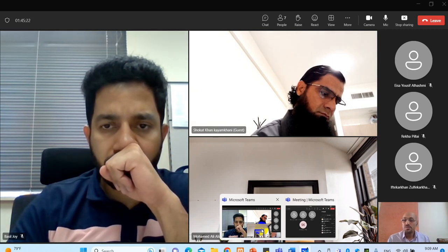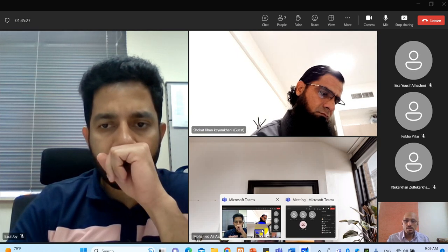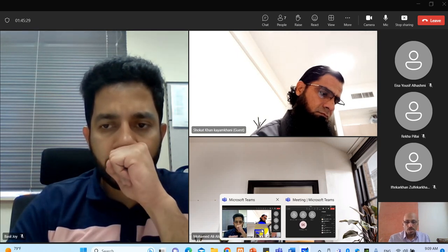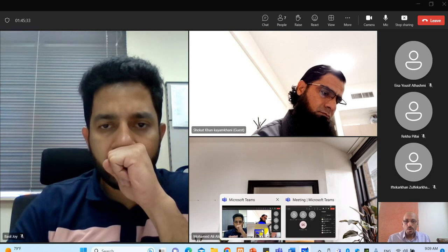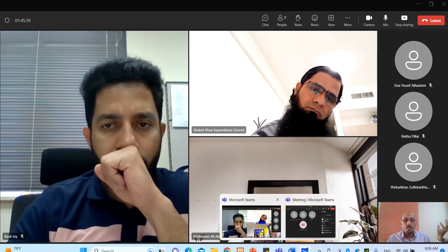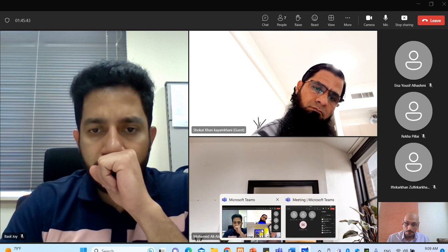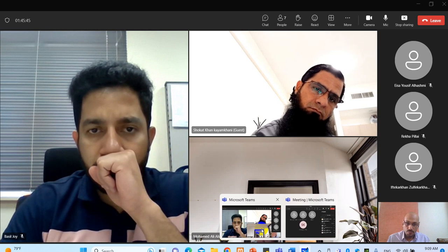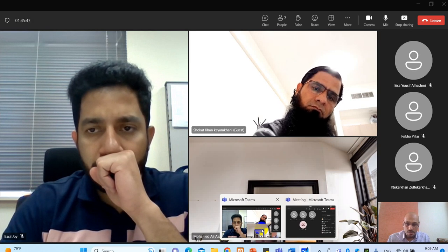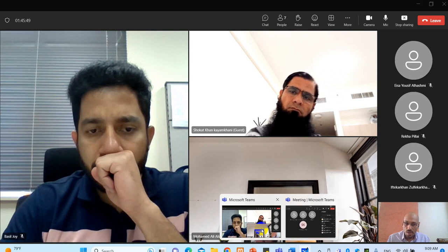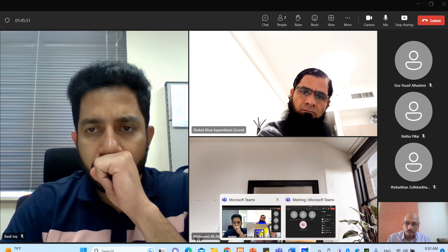What if you increase the number of trips? When you're counting this overhaul time, for example 12,000, you count the running time plus the equivalent hours times the number of trips and starts, right? Are you doing this or what? How do you calculate the number of running hours?